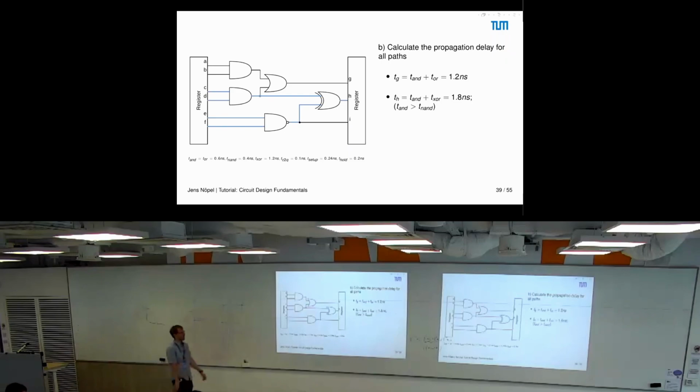Or you think about in what gates they differ, which is this one and this one, and which one has the larger propagation delay. It's the AND, right? So we just use this path here and calculate the time for TAND and TXOR and come to 1.8 nanoseconds. For TI, it's very simple, just one gate, so 0.4 nanoseconds.